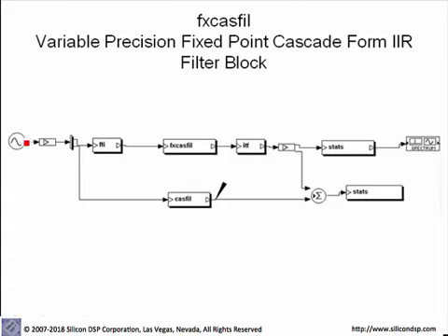So in this case, again, we are using a sine wave as a stimulus, passing it through a gain in order to get it to a 12-bit number. We have the floating point to integer, and the integer to floating point. This is 100% fixed point arithmetic in this block. The floating point block is also implemented using the same stimulus, and we're able to subtract the results of the floating point from the results of the fixed point and obtain the RMS error.